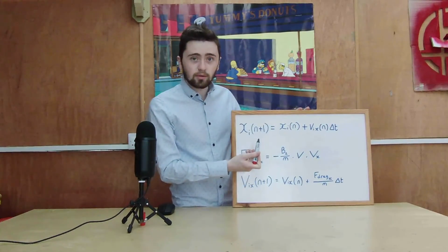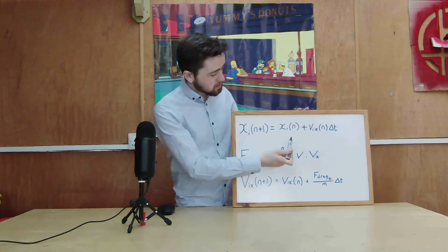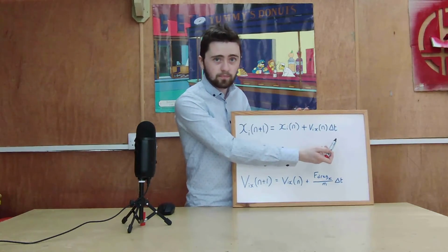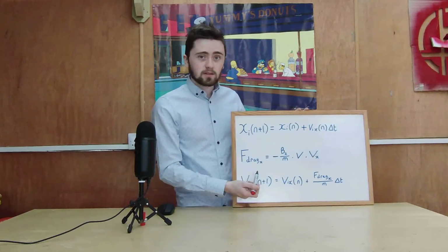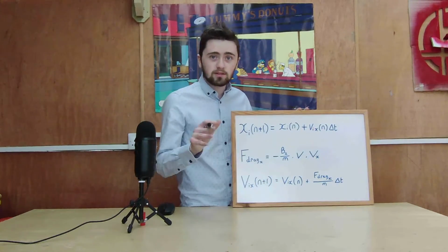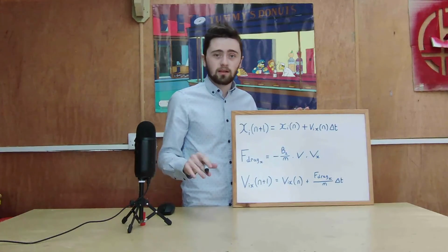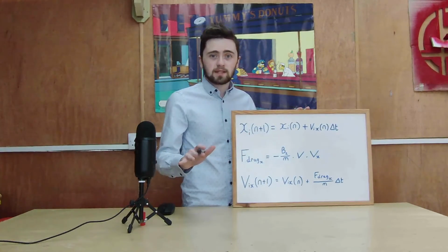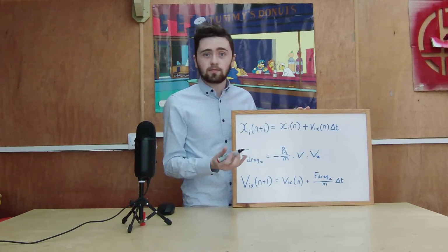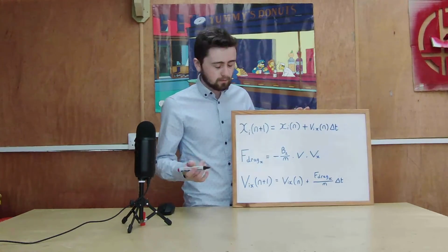The next location of the projectile is dependent on where it currently is, plus its velocity by a time step. Now, the drag it's experiencing is dependent on a property B2. Now this is derived from the shape of the projectile. It is almost impossible to calculate, so it's always approximated. And for our large cannon shell, we're going to take a value of 4 by 10 to the minus 5.